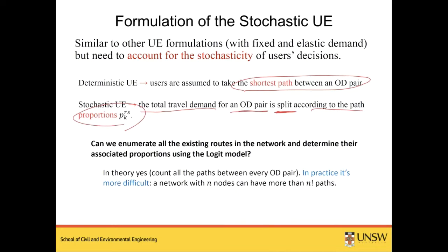So whatever probability I calculate for my possible routes, 70%, 60%, 20%, the path flows will come from those proportions, regardless of whether the route travel times are equal or which one is greater than the other, except that the travel time calculations and comparisons are implicitly taken into account in the utility function and the logit formula, assuming the utility function carries that travel time variable in it, right?